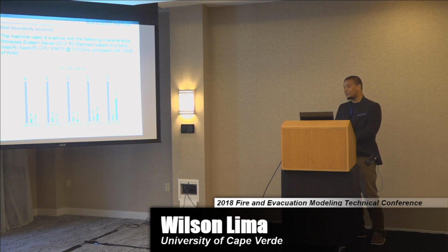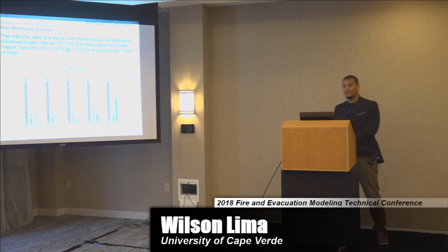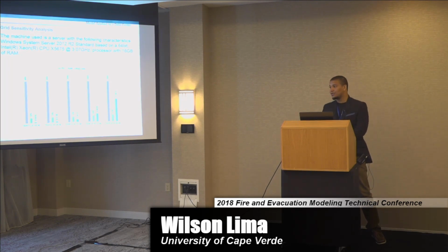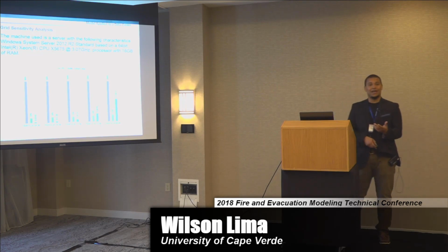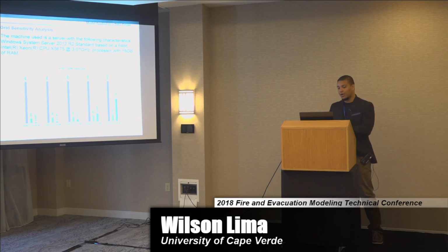But what surprised us is the runtime of our simulation, where we could see for the 0.12 meters, where we use the same value, about 3 hours of difference between the same cell dimensions. It was an unpredictable result. We didn't expect this value, so we are trying to do more grid sensitivity analysis in this model to improve our work.